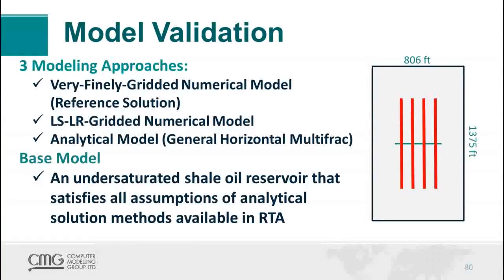But remember, we modify the conductivity of that fracture so that the equivalent conductivity is exactly the same. And we also, when using non-Darcy flow, modify the Forchheimer equation coefficients so we get the same non-Darcy flow pressure loss that we would get if the actual frac width were taken all the way down to prop frac width.